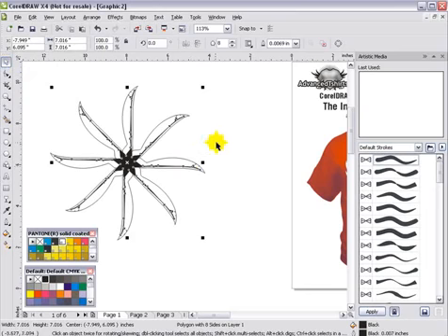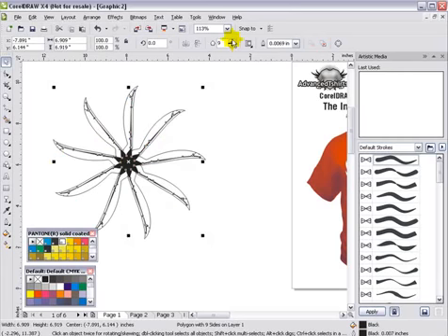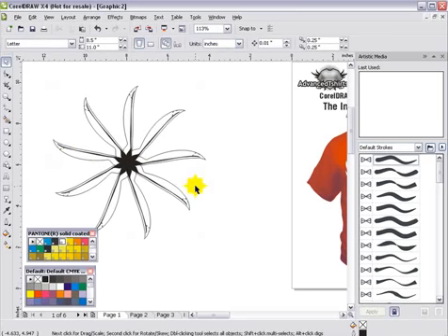Now, one of the great parts is that now that I've set this up with all these curves, you'll notice that if I want to, I'm still a polygon even though I've got these feathers set up. So if I change this to 9, I'll create another feather. If I select where my plume center was and bring that up to 9, you'll notice that it holds its registration inside of my feather. So this is a good shape for me to start with.